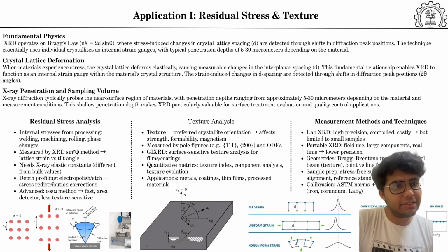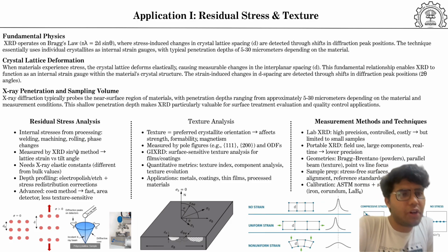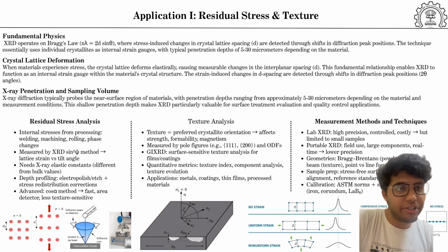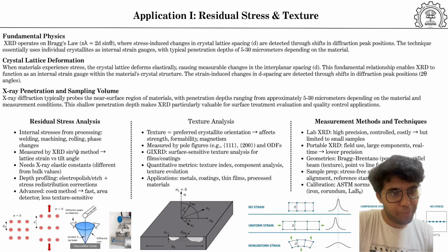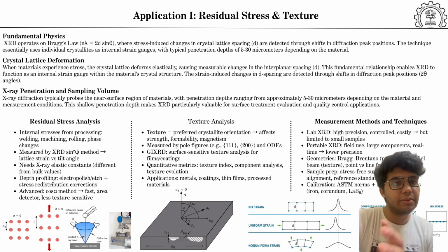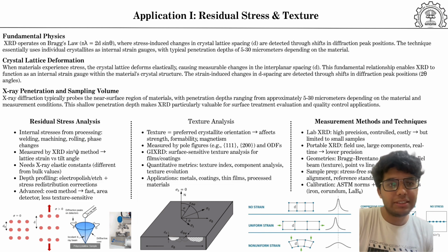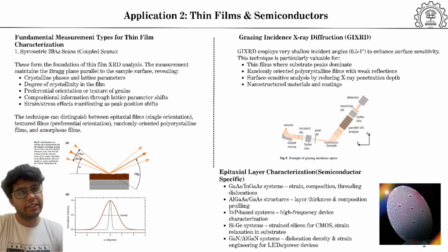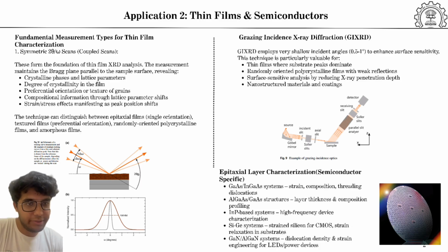Portable XRD systems exist for field use, though with lower accuracy. And we always rely on careful calibration and stress-free reference samples to make sure results are trustworthy. So in short, XRD lets us non-destructively probe both the stresses locked into the material and the crystallographic textures that influence their performance. The second application of XRD, which I think is interesting, is thin films and semiconductors.